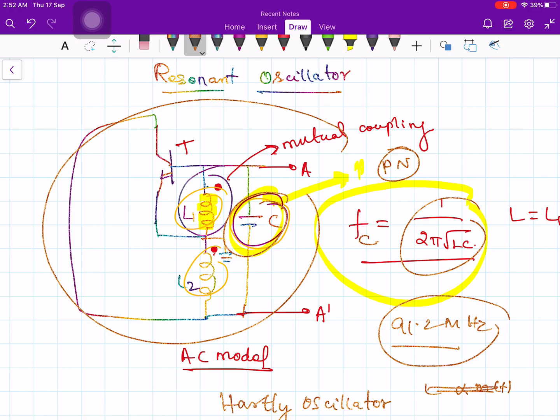However, as far as frequency stability is concerned, what can we say here in this direct method? Will it be as good? No, the answer is no, because we don't have a crystal oscillator in this circuit. The feedback circuit, that is the LC component, does not come from quartz crystals. They have to be separately realized because one of the components is the variable capacitance. The capacitance by its very name is variable, and therefore it is subject to drift and all the effects associated with any passive or active component. So all the drift effects will be present, and you cannot show that the omega naught you are going to get will be constant for all time. It's very simple to show because it is a function of time. So the frequency stability is greatly affected in this case.